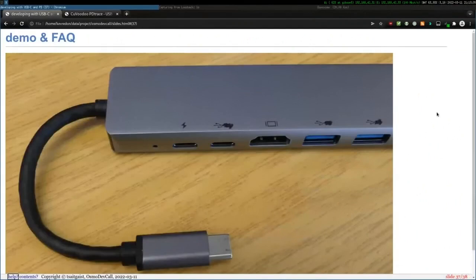Yes. So what uses have you seen on the SBU pins? Sideband use. I've seen 2 users. I've seen it in USB 4. For USB 4, you need these 2 wires, these SBU wires. The other one I've seen is audio. Often when you have a smartphone where you can plug a converter to have USB-C to 3.5 millimeter jack, this is where it goes through. It uses the SBU pins. It uses sideband use pins.